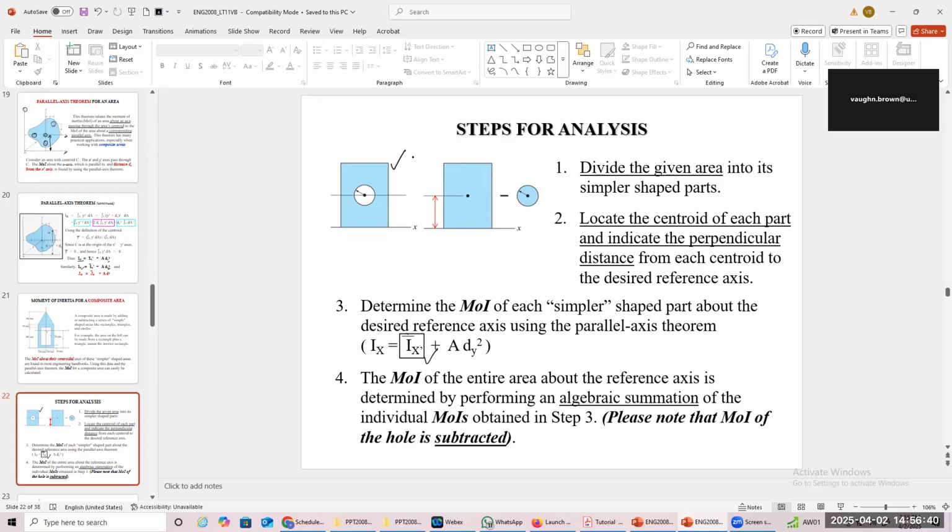The first part, you remember that? If you have Ix, the first inertia, which is Ix prime, that you find is going to be BD cube upon 12. You get that from the table because the figure is a rectangle. Whatever the type of figure is, the first inertia you find is the standard inertia of the body shape.